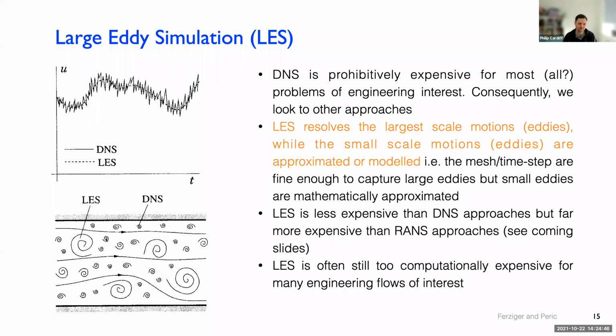So at any one point in space, if we monitor the velocity, LES would give you maybe this smoother line capturing the big vortices, but DNS would have every tiny vortex. So it'd have all of this totally random turbulent behavior.